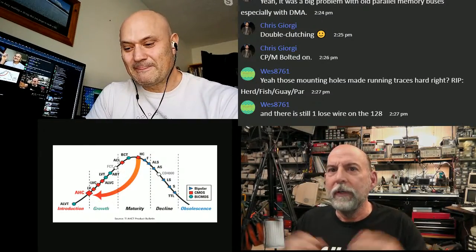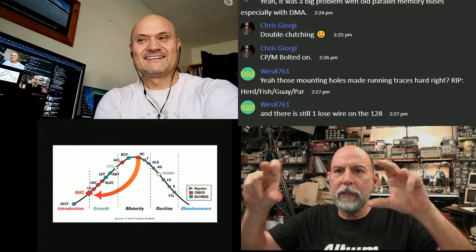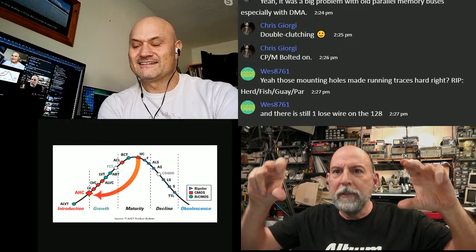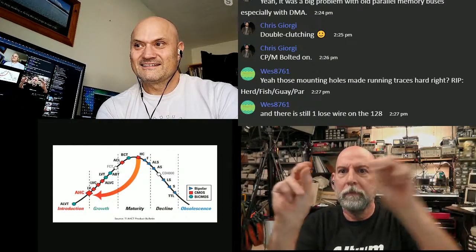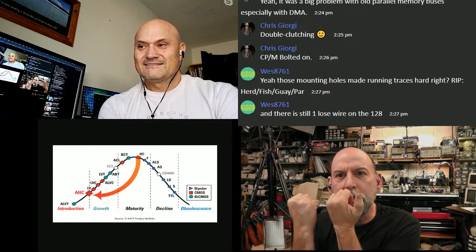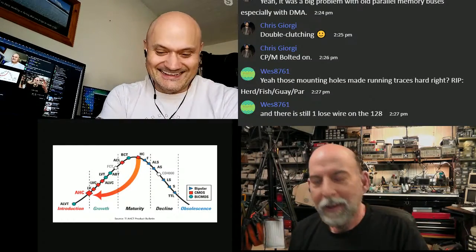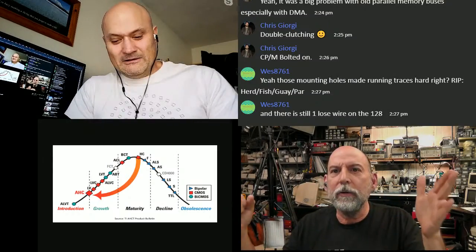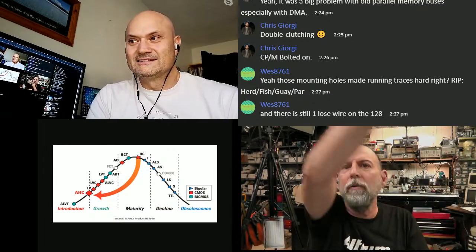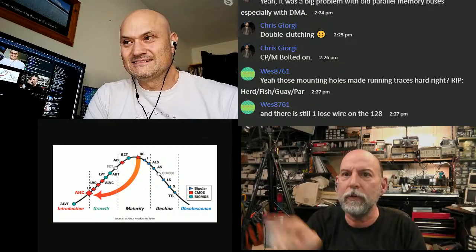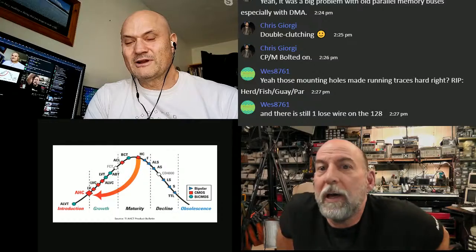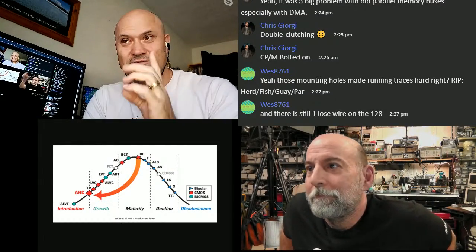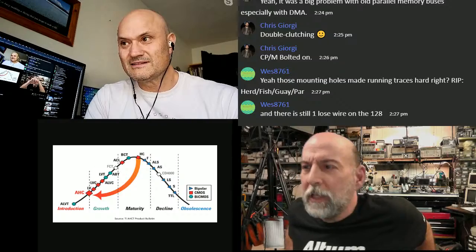That's worth repeating. So what the problem was is the bus, it was good between the 6502 and the DRAM, but the Z80 was trying to insert itself, and instead of driving it nicely from the end, it was driving the middle. It's like blowing a flute in the middle instead of from the end, right? And so what I did was I added a wire, so instead of reflecting off of it, it kept going. I made the wire go around to the beginning, so now it's a ring. There's no reflections. I mean, there's interferences and stuff, but I removed the stub. It wasn't the whole bus, right? It was just one of the bits that was doing A10, address line 10.